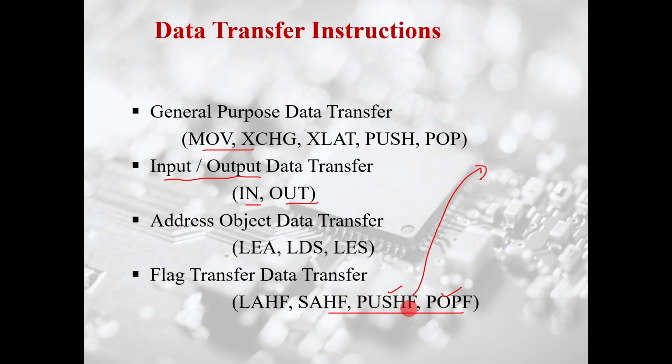We learnt about the push and the pop, right? So whatever is the data in the flag register, that is going to be put into the stack. When I say pop, it will bring back this data into the flag register. So this is nothing but push F, and pop F is nothing but, when I write push F, the contents of the flag will be pushed into the stack.